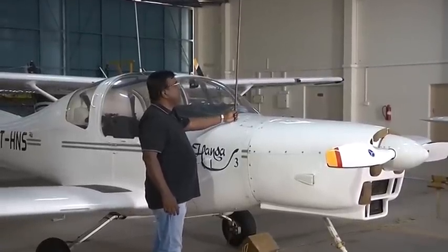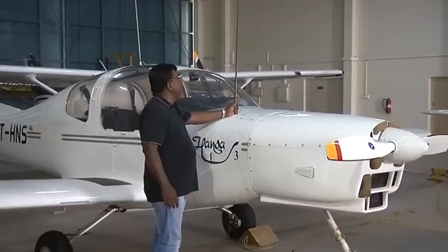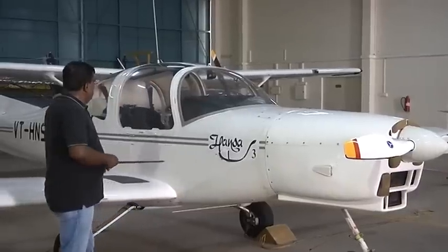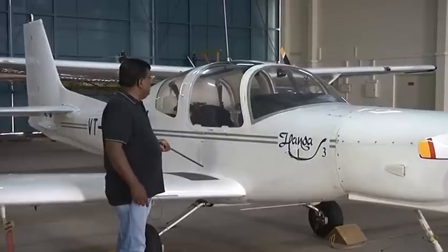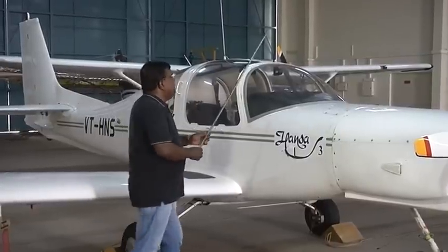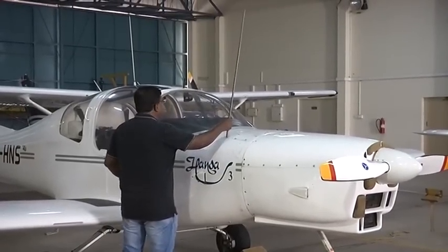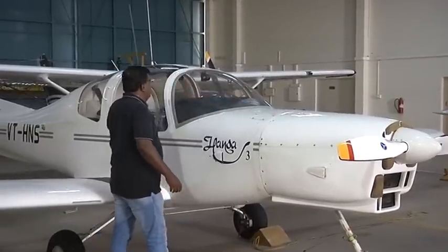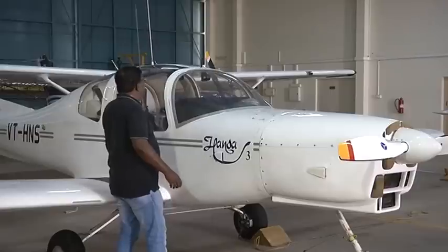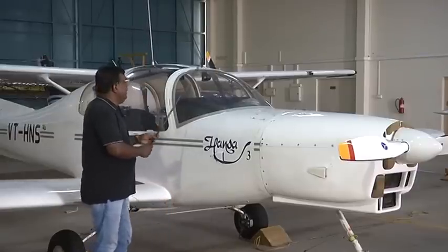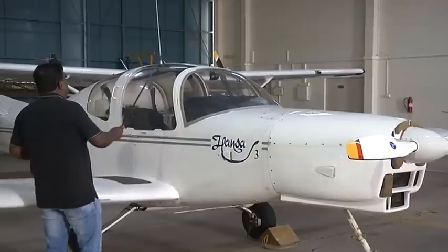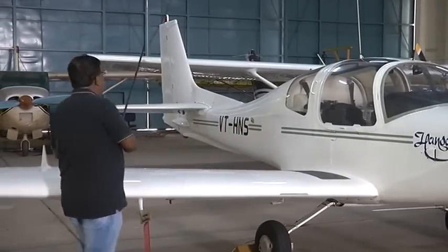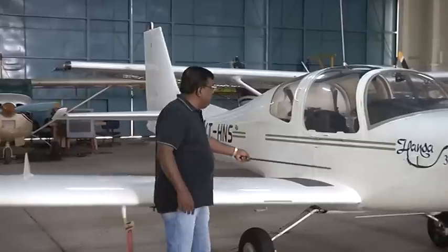Okay? Let us take the example of lift. For a small angle of attack, if this is the lift direction, but I am writing the equation of motion assuming the whole mass is at the center of gravity somewhere here, then I need to transfer this force from here to the center of gravity. And once I transfer a force from here to a distance, I know that I can transfer it with the force as well as the moment. Okay? So because of this fuselage, there is one force, which is lift, and a moment. Similarly, take the case of a wing. So there will be a force, the lift force. I again transfer it with a moment to the CG.